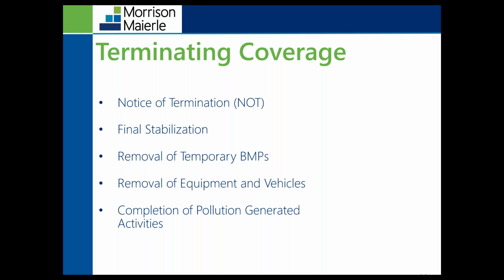Also, you have to make sure that pollution-generating activities have been completed, equipment and vehicles removed, and temporary BMPs removed. It is important to know that this NOT needs to be submitted prior to the first of the year if you have reached the requirements to terminate your coverage.